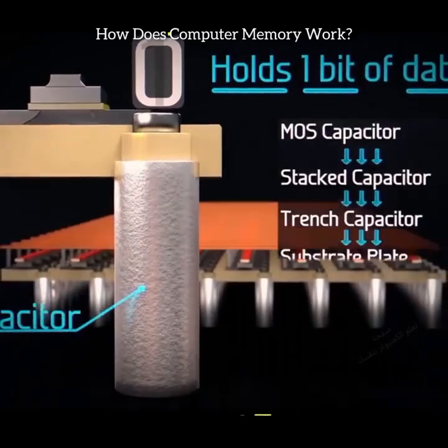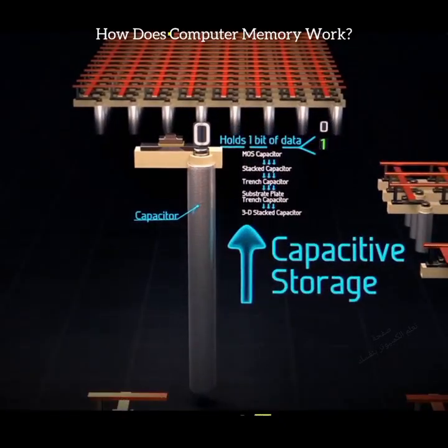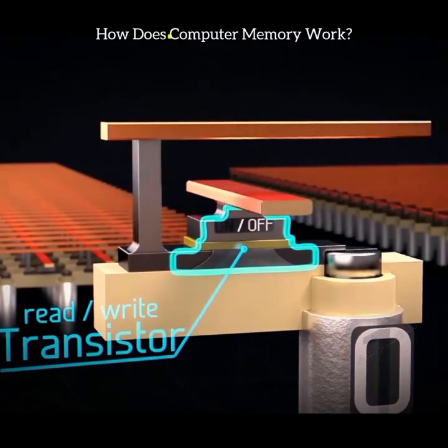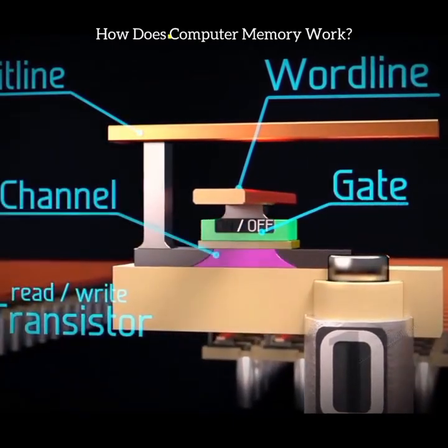Designs of capacitors are constantly evolving, but in this trench capacitor, the depth of the silicon is utilized to allow for larger capacitive storage, while taking up as little area as possible. Next, let's look at the access transistor, and add in 2 wires. The word line wire connects to the gate of the transistor, while the bit line wire connects to the other side of the transistor's channel.